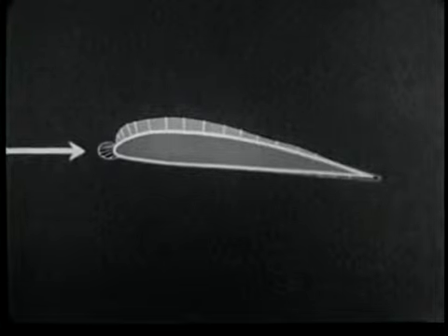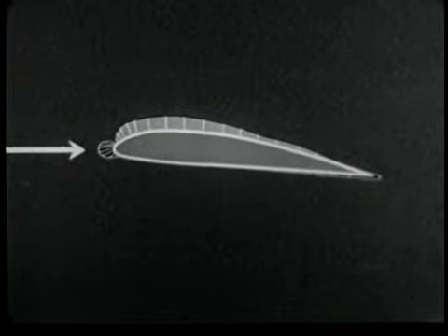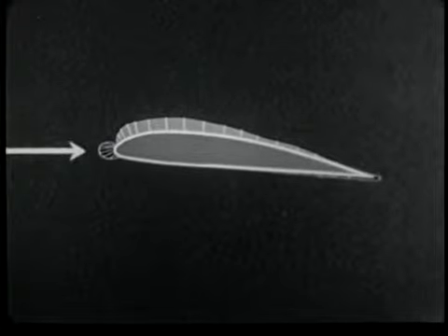As the angle of attack is increased, the positive pressure bulb moves lower down on the leading edge and back along the lower surface of the wing, enclosing the trailing edge. The negative pressure distribution remains fundamentally unchanged, although its values are greatly increased. This diagram indicates that the wing has begun to exert a considerable lift.